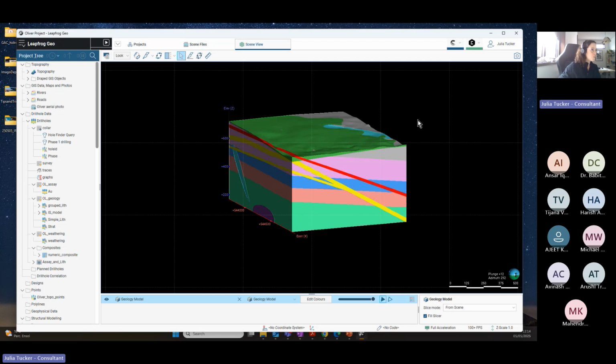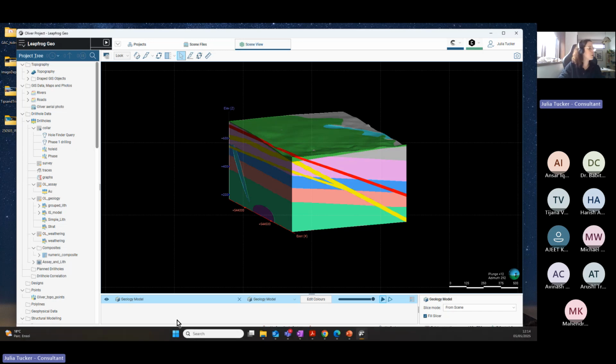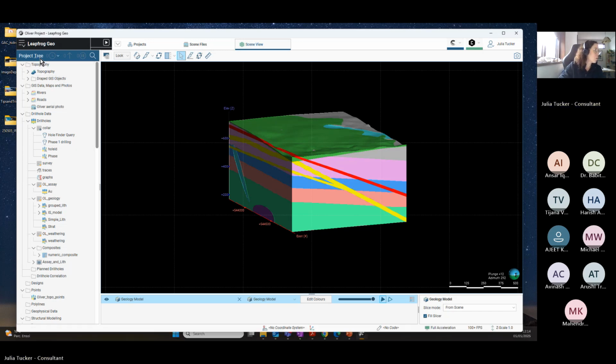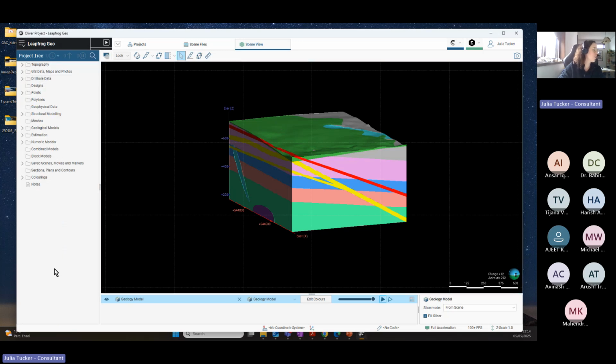One thing I wanted to mention before that: you have seen that we have a lot of files here. If I want to see my project tree a little bit cleaner, what should I do? Right click on the top and say collapse all the rows. This is the same process if you want to detach the project tree and have it in another place of your software, or if you want to hide the project tree. But here we are just collapsing. Why? Because collapsing, we can understand a little bit better what we are trying to reach.